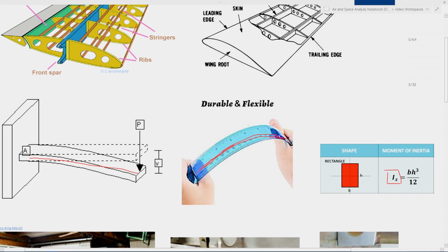But imagine if you rotate this 90 degrees. So now, instead of trying to bend it in the direction that it's thin, imagine you're trying to bend it like this. This is the ruler, we have all of our measurements here. Put your hands here and just try to bend it like that. It's going to be very, very difficult, right? You're probably not going to see any perceptible bending because it's going to be almost entirely stiff from your perspective to try to bend the ruler along the direction that it is tall.